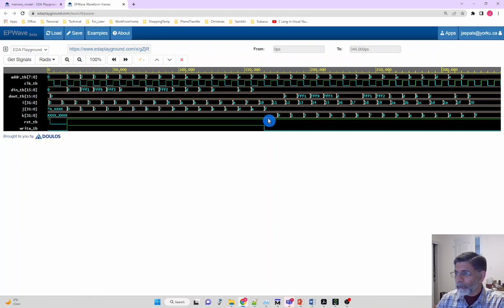But we can confirm that when we are reading the memory. So here you can see we are reading the memory, and data out, when we're reading location 1, value is 4, which is what we wrote here. Then the next value is FFF1, same here, FFF9, and so on. And the numbers keep on repeating. D is on during 2 locations, we see that, and then C and 9. So the memory is behaving as we expect.